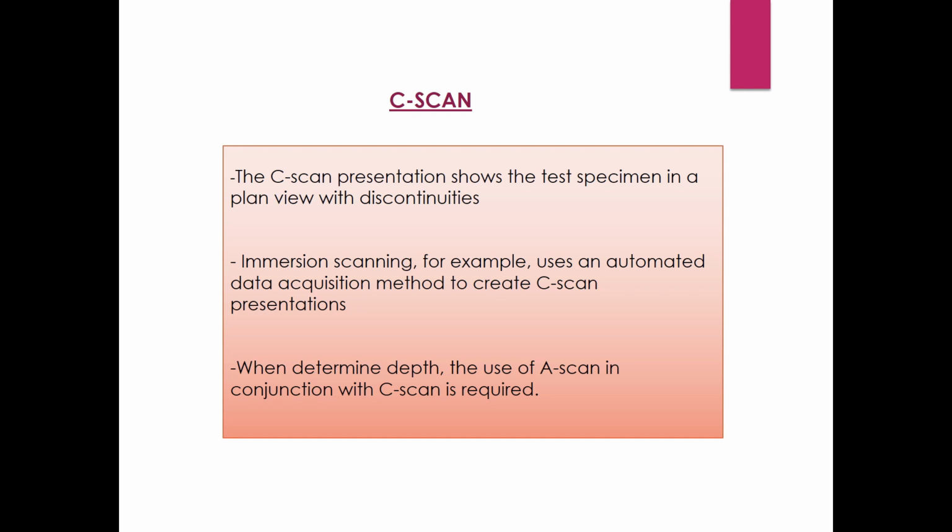The last one is C-scan. The C-scan presentation shows the test specimen in a plan view with discontinuities. Immersion scanning uses an automated data acquisition method to create C-scan presentations. When determining depth, the use of A-scan in conjunction with C-scan is required.